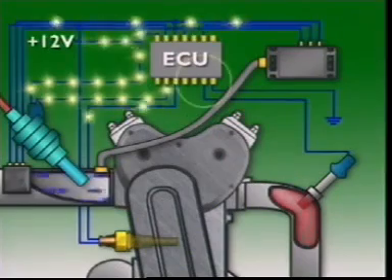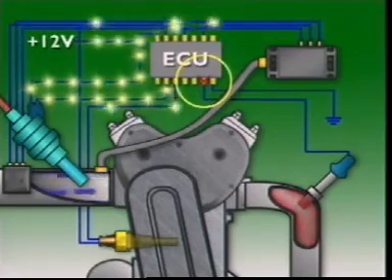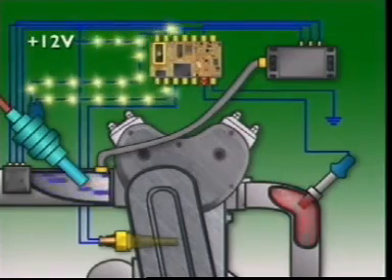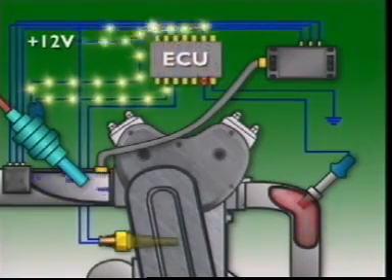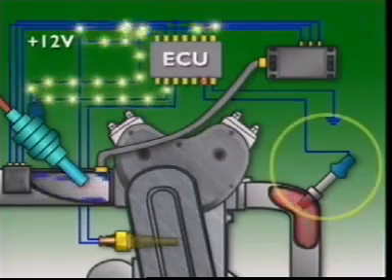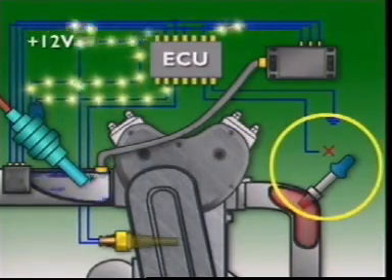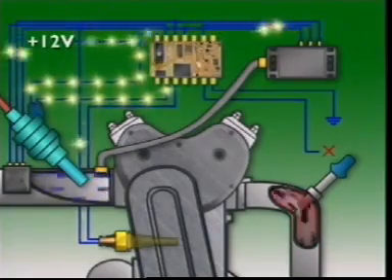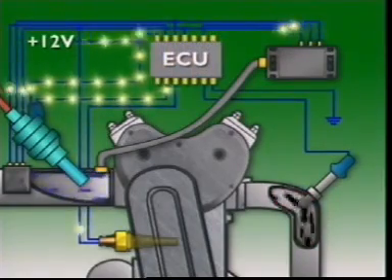Open loop can mean there is feedback to the control unit, but it is ignored, and the fuel settings are then determined from the programmed memory. Alternatively, open loop means that there is no feedback to the control unit. In that case too, fuel settings are determined from the programmed memory.